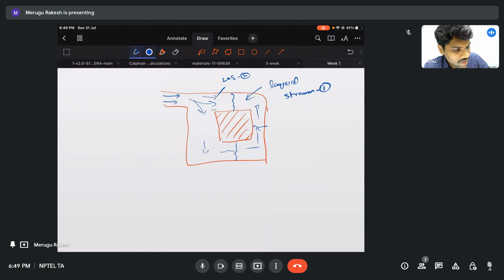If the two liquids are meeting, because of this difference in the cooling rates, we can see a small appearance of a crack. They are not fused well because of the lack of cooling, because of the lack of heat for them to combine and form a seamless design. So we can see these casting defects mostly on hubs.